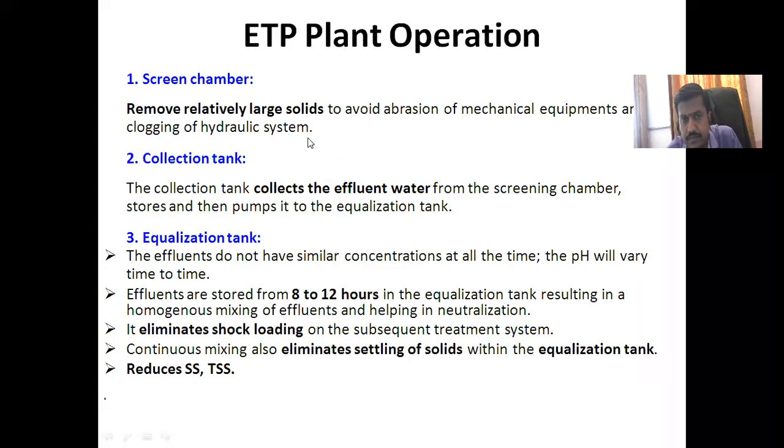Next, plant operation. How are these ETPs going to work? Screen chamber, everyone knows now. I will take it a little bit faster. In the screen chamber you remove the large solid particles to avoid abrasion of the mechanical equipment and clogging of the hydraulic system. It removes the relatively large solid particles to avoid abrasion of mechanical equipment and clogging of the hydraulic system.